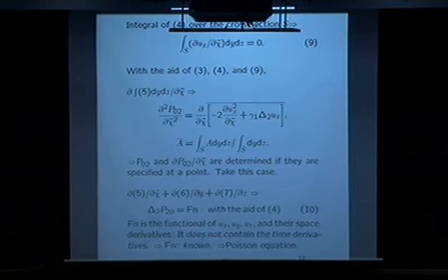Now we take the divergence of the momentum equation as you do in the Navier-Stokes equation, and from the solenoidal condition, the time-dependent term disappears.